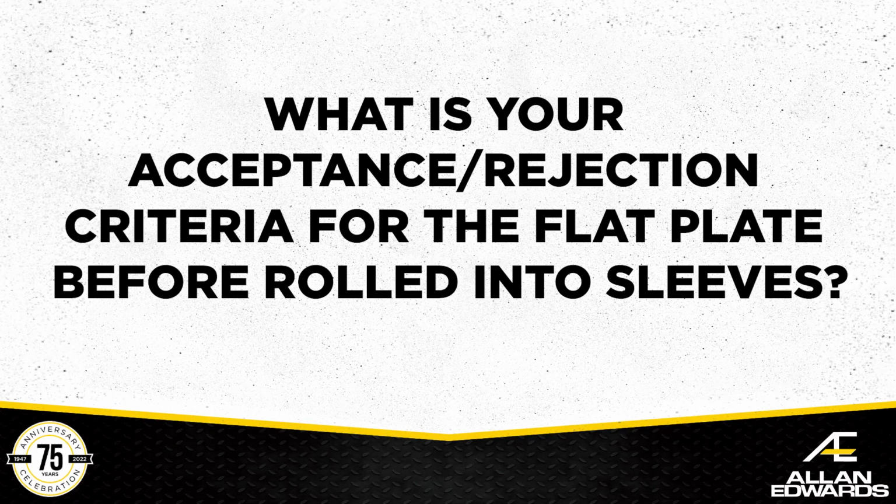The next question was, what is your acceptance rejection criteria for the flat plate before rolled into sleeves? So the specification is ASTM A578 to acceptance criteria A with an S1, which is 100% scan. And so that is the standard.